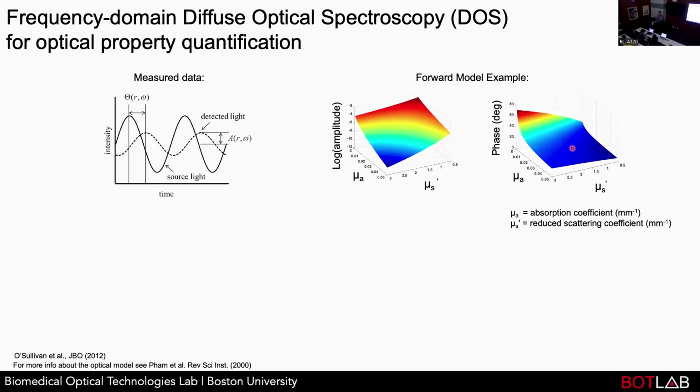And every detector has some capacitance. Capacitance, together with some of the intrinsic resistance, acts like a low-pass filter. And you have higher capacitance the larger the active area of the detector. You want a large active area detector to measure a lot of these photons, especially at large source detector separations. But there's roll-off. It's very hard to measure at a gigahertz at 30 millimeters source detector separation.